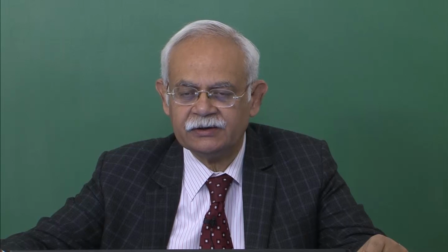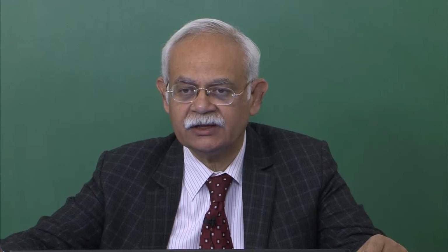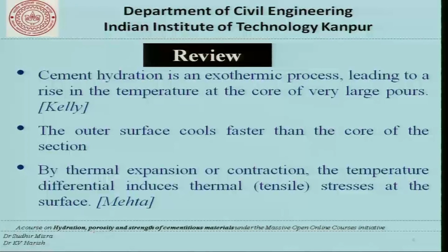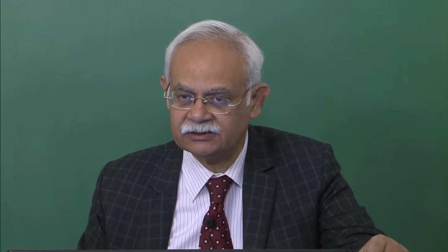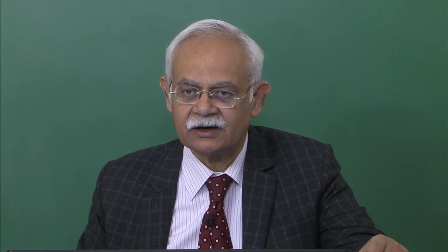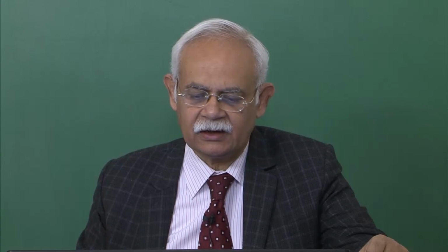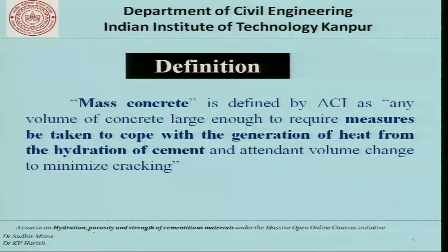The surface of concrete tries to remain in equilibrium with the environmental temperature. By thermal expansion or contraction, the temperature differential between the core and the surface induces thermal stresses which are tensile in nature, and that is what we will study today. And since concrete is essentially a material which is weak in tension, this introduces cracks in concrete which are referred to as thermal cracks.